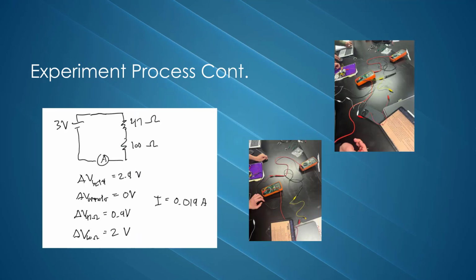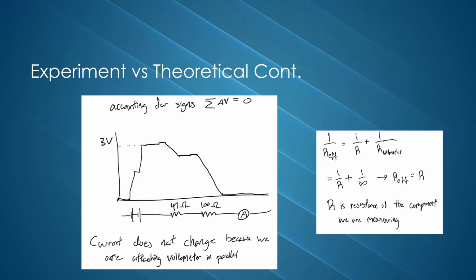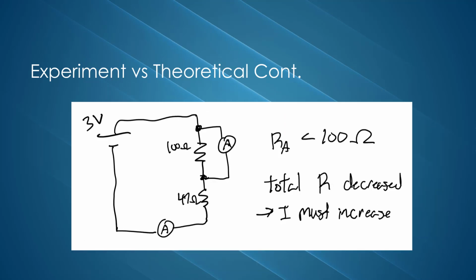Then, we use our voltmeter to measure the potential difference across each component of our circuit. And that gives us what we'd expect if we would have just calculated it using V equals IR. Here we can see the loop rule. We start at 0, go up due to the batteries, flatline at the wires, and decrease at the resistors to end up back at 0.